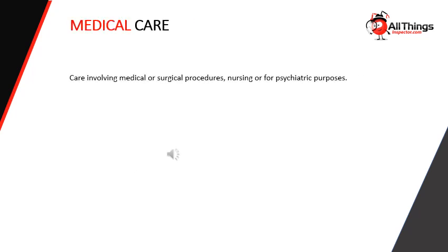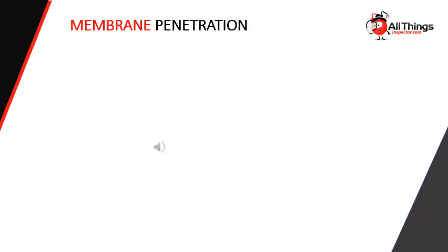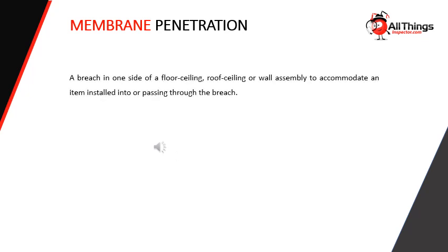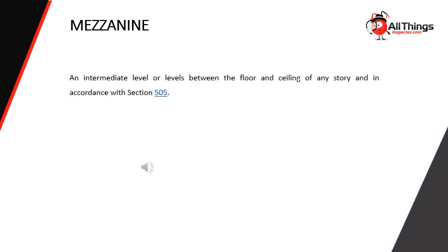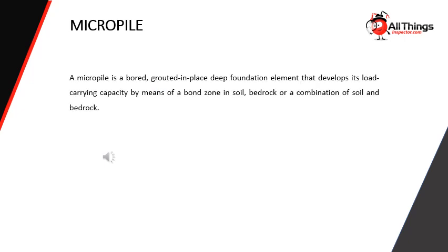Medical care. Care involving medical or surgical procedures, nursing, or for psychiatric purposes. Membrane penetration. A breach in one side of a floor-ceiling, roof-ceiling, or wall assembly to accommodate an item installed into or passing through the breach. Mezzanine. An intermediate level or levels between the floor and ceiling of any story and in accordance with Section 505. Micropile. A bored, grouted-in-place deep foundation element that develops its load-carrying capacity by means of a bond zone in soil, bedrock, or a combination of soil and bedrock.